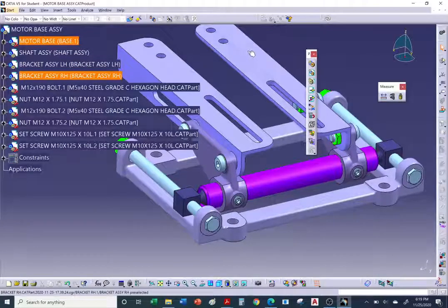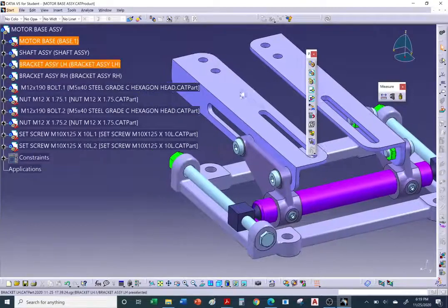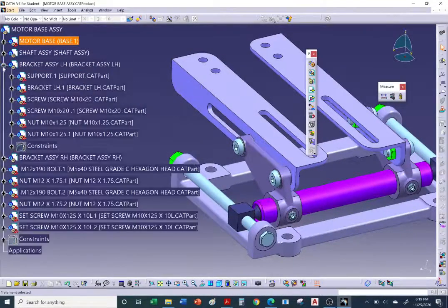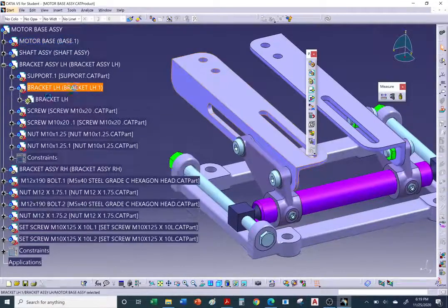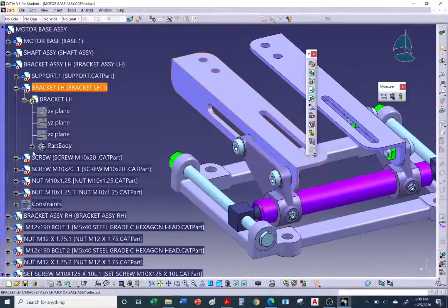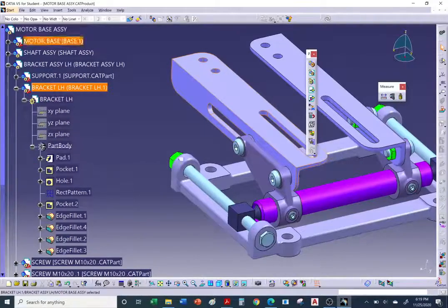You save memory. Okay, so if I wanted to work on the mounting bracket, if you hit the plus once again, you'll see that there's no history. It's like, hey, what happens to its history? You can either double click on the solid or double click here on the tree, and it'll load its history of how it was created.